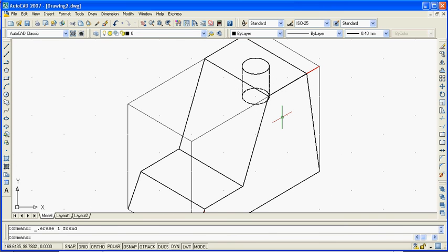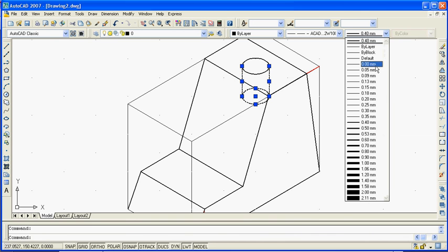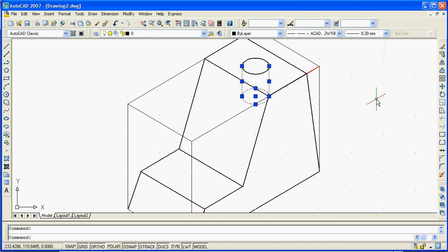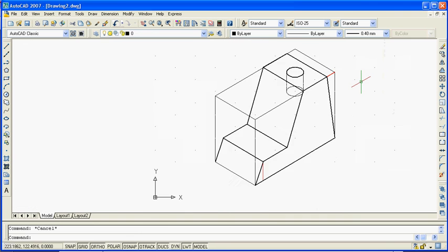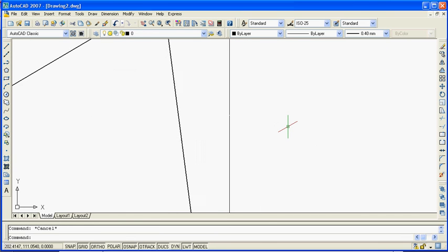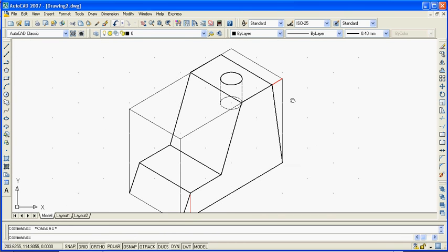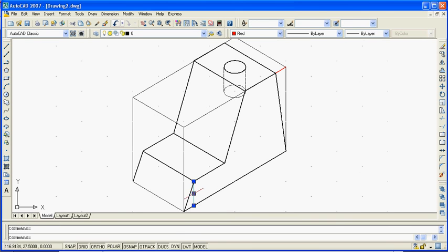But you have to remove this line. No need. Right. That is the end of this exercise. This inner dashes can be mild, so you can change this line type scale to around 20. Okay. Undo. It can be 20. So it can be dashed, but it is mild. It is not visible. That is the end of the exercise.